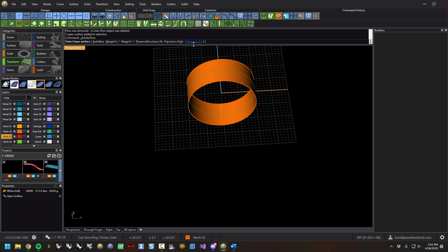Depending on how particular you want to be about when it puts an object from the base up to the target. If your tolerance is too fine, like perhaps 0.01 or 0.001, then it adds more ISO curves that it needs to maintain the integrity of the surface.